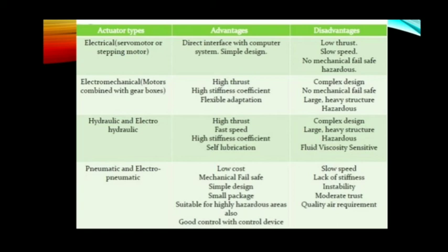An electro-pneumatic actuator can be briefed as integrating pneumatic and electrical technologies, consisting of electrical control systems operating pneumatic power systems. The signal medium is the electrical signal, and either an AC or DC source is used. The working medium is compressed air. In this, solenoid valves are used as the interface between the electrical and pneumatic systems. That is, the final control valve is activated by solenoid actuation.